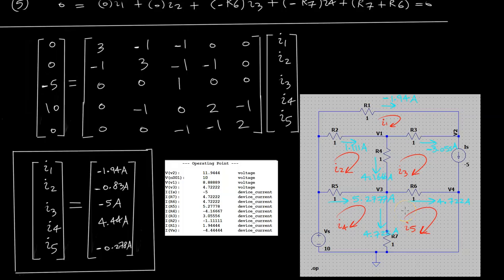This is a little bit tricky to verify because of the interdependencies of all these meshes. You basically have to do some manual branch current calculations. LTSPICE doesn't directly tell us the mesh currents, and because all these variables are simply mesh currents, we have to do some manual calculations. So I start with a node where the mesh current is the branch current. For example, this